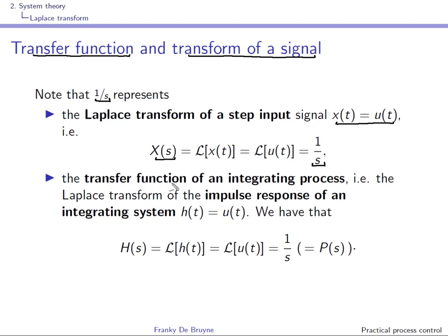Well, 1 over s can also be the transfer function of the process, and in this case H(s) is 1 over s, and this process is an integrating process.